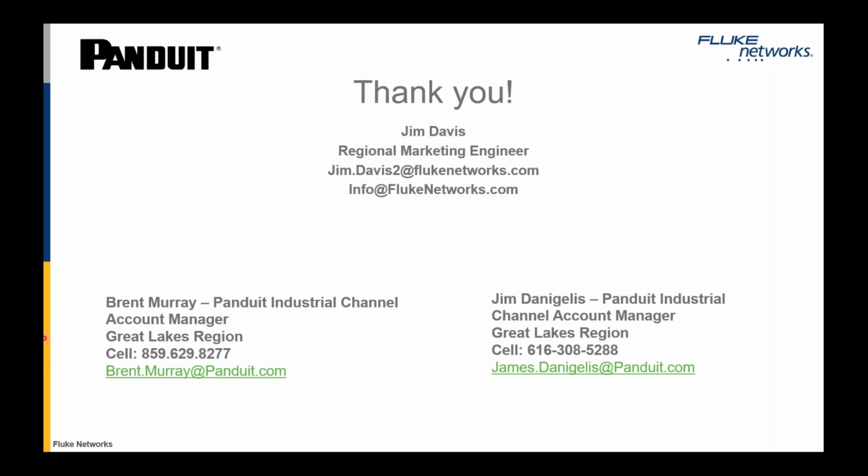It's got 2-pair cable and 4 conductors, right? It also has Category 5E performance, and it's associated with using the cabling for a smart block type application or a smart IO application. So the D code M12 is used for that purpose.